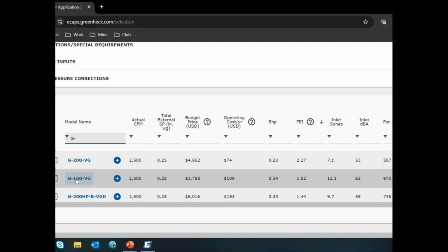I don't want maintenance. If you were to ask me, in our industry we are definitely moving to direct drive fans on a whole. Especially the big three, what I consider the big three, and that's simply this: health, government, and education, right? I see very often that they are pushing hard to direct drive fans. No one's got a larger maintenance department than they had 5 or 10 years ago, right? We're all doing more with less. This is the world we live in.